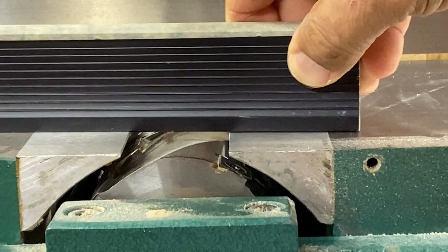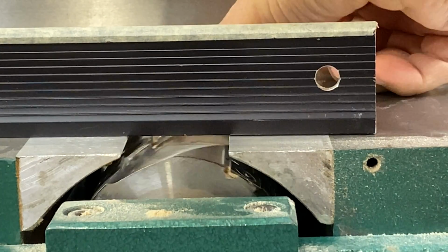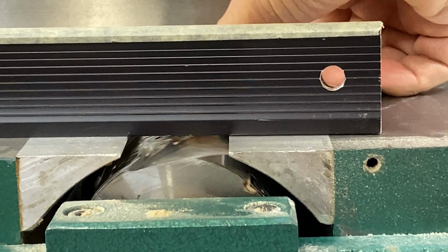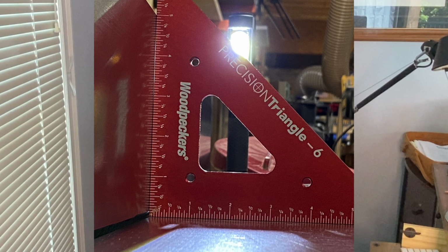Be sure to check both ends of the cutter head. Consult your owner's manual for instructions on how to adjust your outfeed table if needed. Then adjust your fence so that you cannot see any light when a 90-degree triangle or square is held up to it. My fence is dead 90 degrees. But it's interesting to note that there is a slight dip in the fence near the top, although the top is touching. That's good enough for me. Also, coating the table and fence with paste wax allows boards to glide more easily.